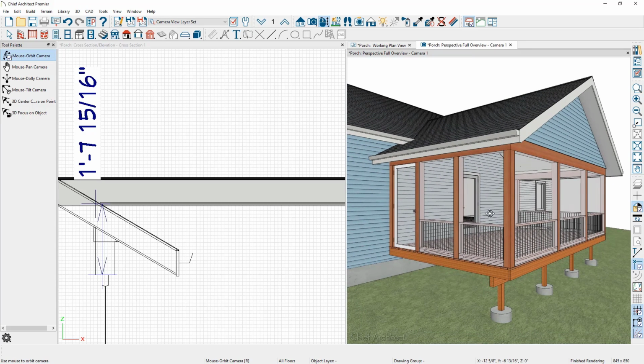Now, one thing you might do is you may have noticed that when we added the door, we had a post come up on the other side of the door, and we also have a post in this area, and our panel looks a little tight. The reason this extra post generated is because our maximum on-center spacing between posts is set at 96 inches.